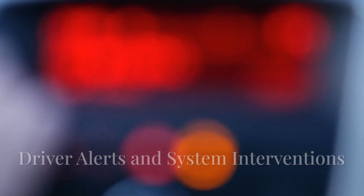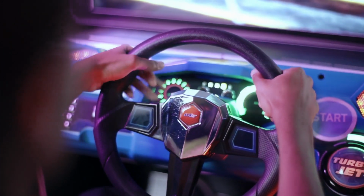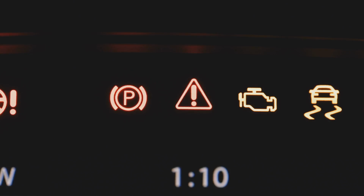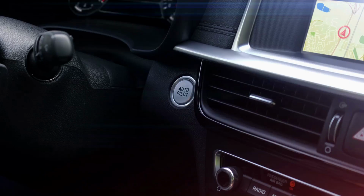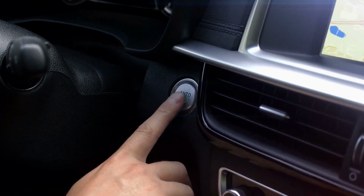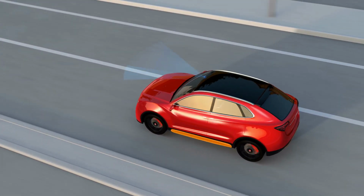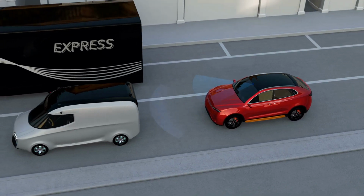4. Driver alerts and interventions. Based on the analysis of the data, ADAS can either provide alerts or take autonomous actions. Alerts. If the system detects a potential risk, such as an imminent collision, lane departure, or an object in the blind spot, it will notify the driver through visual, audible, or haptic signals. Interventions. In some cases, the system may intervene to prevent accidents or assist the driver. For example, automatic emergency braking, or AEB. If the system detects an imminent crash, it can automatically apply the brakes to avoid or mitigate the collision.